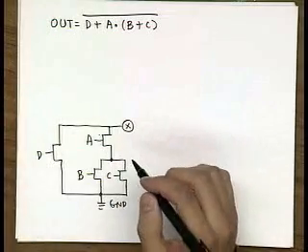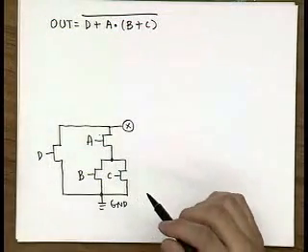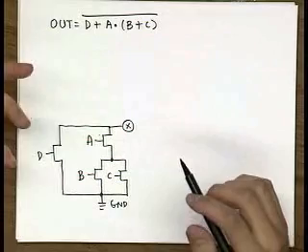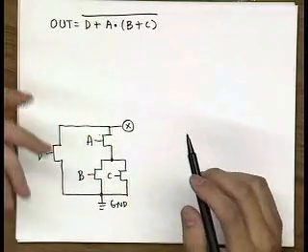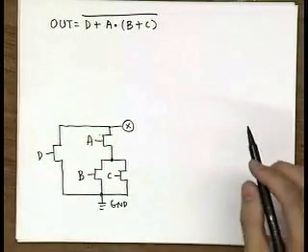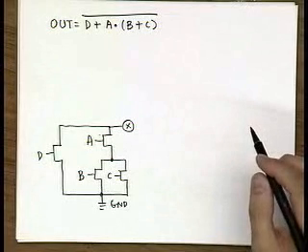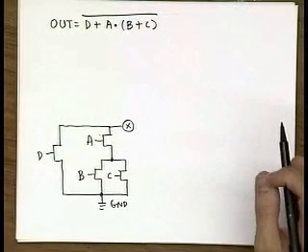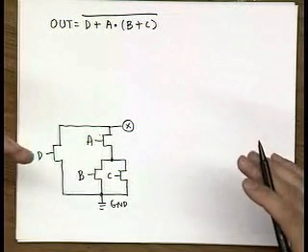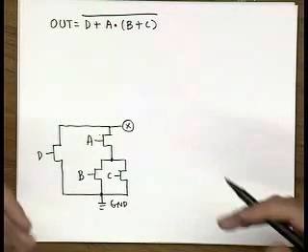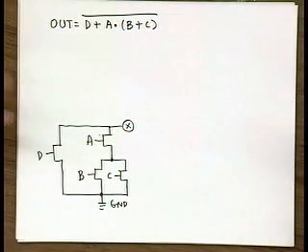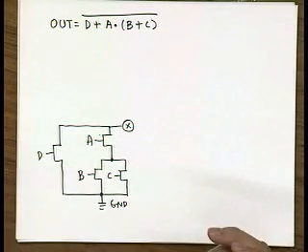Now once you have a pull-down network, you can use this duality principle to easily construct a pull-up network. I will show you one very useful method that you can use to automatically transform your pull-down into your pull-up network, and for that we will use graph theory. Everybody's heard about graphs: you have nodes and edges that represent transistors in this case.